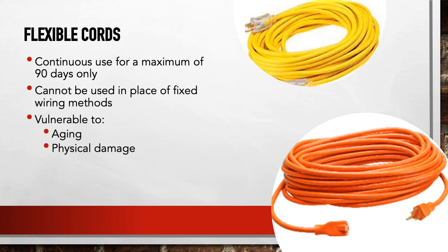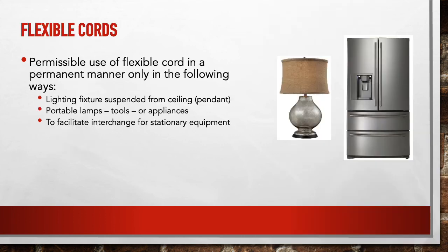The guy about has a heart attack and basically says he needs to redo the whole thing. And I've actually heard of this happening in many cases. People have used these for that purpose. They are not designed for permanent wiring because they do get old, brittle, burn through, have issues with the plugs, receptacles, etc. So other flexible cords that can be used permanently are actually connected directly to the electrical utility.